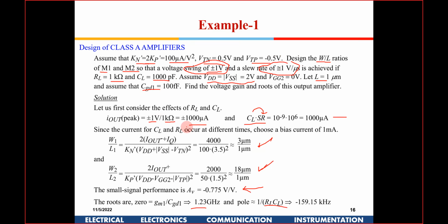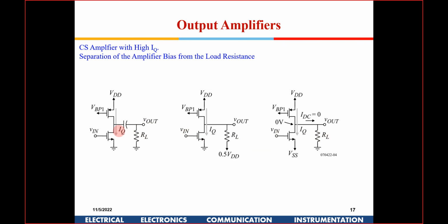So there are certain circuits which are proposed out here. This is one case where you put a VDD by 2 out. If you are putting a ground here, this will be at VDD by 2. Then if you don't want the biasing current to go towards the resistor, you can put a capacitor here. So this is one option available to us.